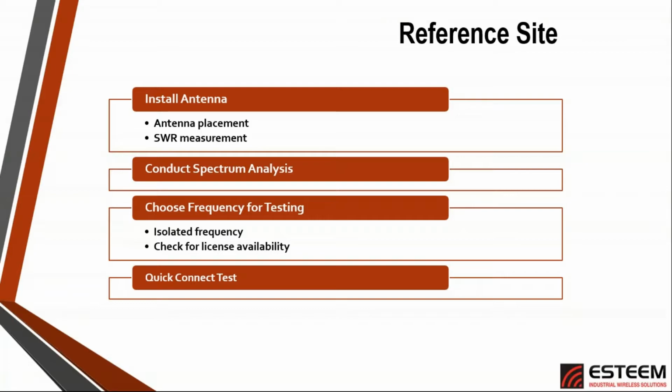The first thing to consider, above all, is that when you install an antenna, we want to look at the placement of that antenna as close as we can possibly get to where it's finally going to be installed. We don't want to install it on the opposite side of the building or out in a clear area away from the building just to make the best test. We actually want to test it as close to where it's going to be installed in the final installation. You just have to work with what you find out in the field.